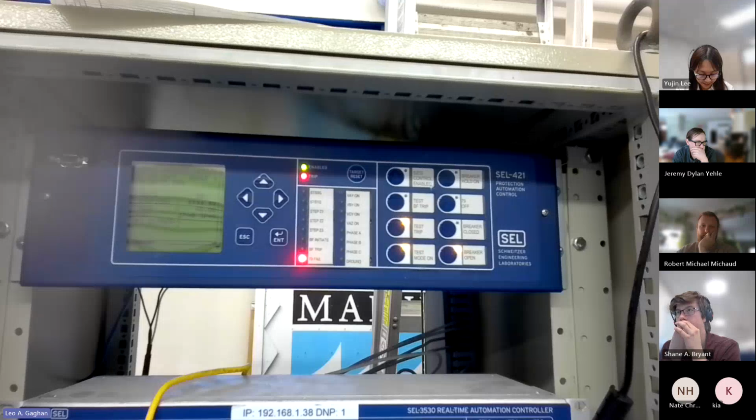You are searching high and low. You usually got thermal guns where you go along the equipment and say, okay, 50 degrees, 50 degrees, 50 degrees, 50 degrees, 120 degrees, let's look there. You figure out what happened, and you remove whatever happened. Once you have done all of your steps to ensure that whatever caused it is gone, then you reset the lockout and close back in.